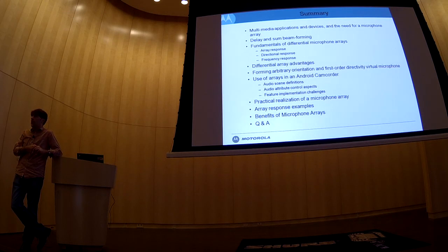Another problem with that is that we have to worry about environmental noise, like a loud car or a bus that has subsonic frequencies. And if we were trying to expand as much of the low frequencies, we will end up with a bad effect, simply because we'll be saturating the mic with a signal that isn't very useful.